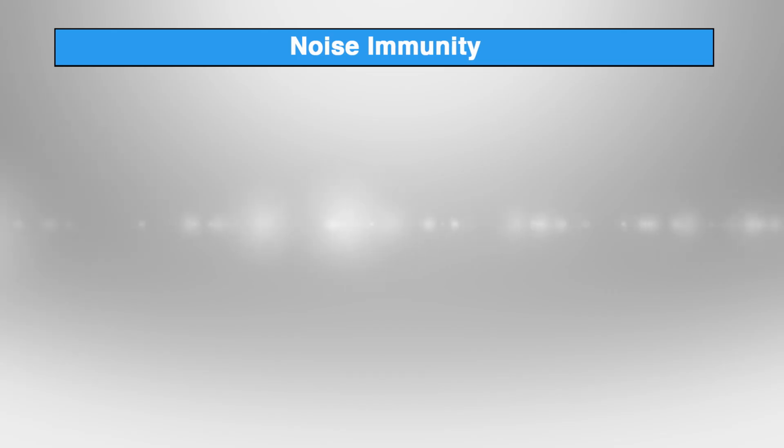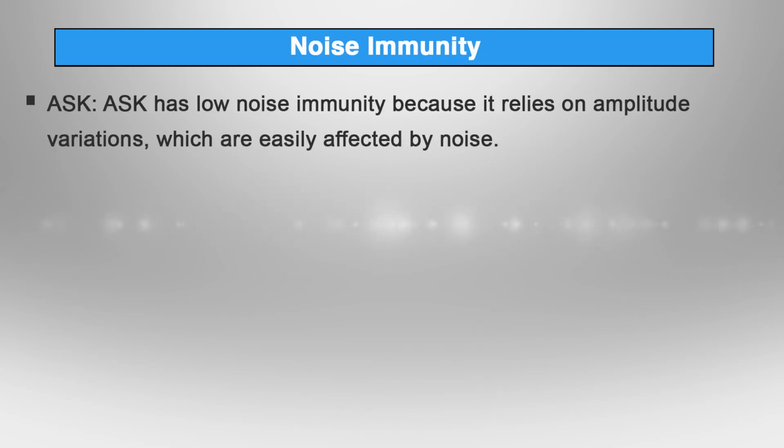Now, come to the third one, that is noise immunity. Noise immunity measures a modulation technique's ability to withstand interference and maintain data integrity. ASK is highly susceptible to noise, particularly amplitude noise. Variations in amplitude caused by noise can lead to errors in data interpretation.